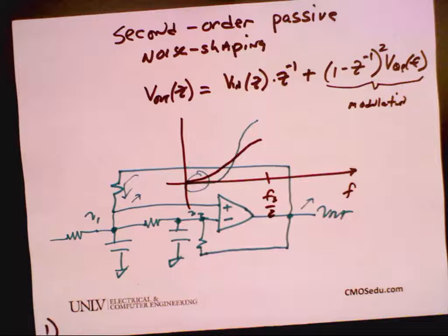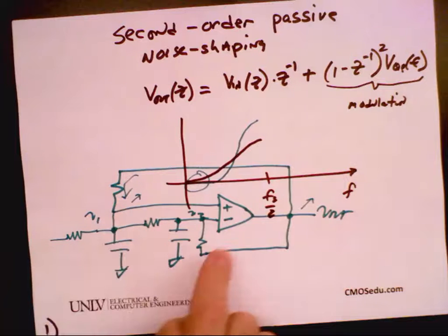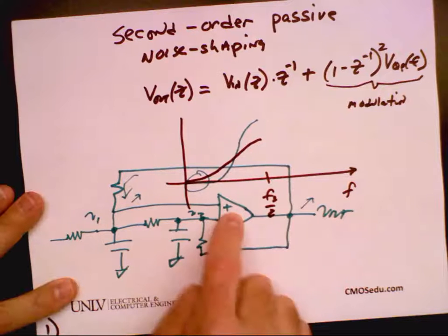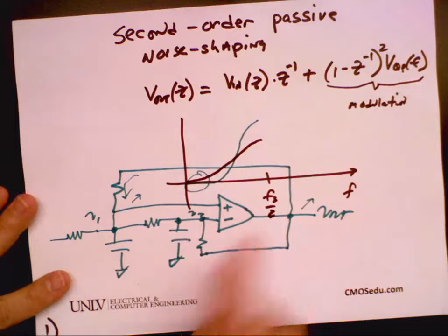Okay, are there any questions? And so one big benefit here is that all the tone stuff we had before, that's not as big of an issue with this topology, because now we have the two feedback loops that tend to randomize things a little bit more. You can tolerate the positive feedback as long as it doesn't dominate. The negative feedback dominates, because the negative feedback here goes directly into the comparator, whereas this one has to be filtered, and so it's a lot weaker influence.